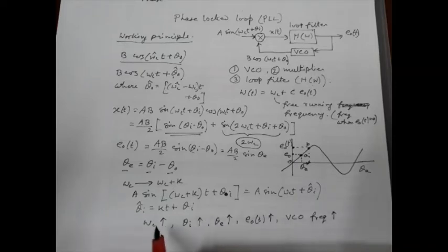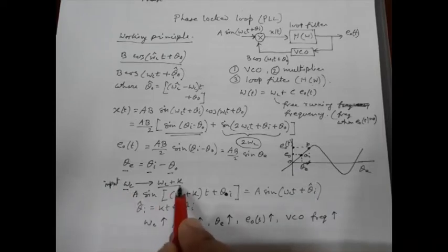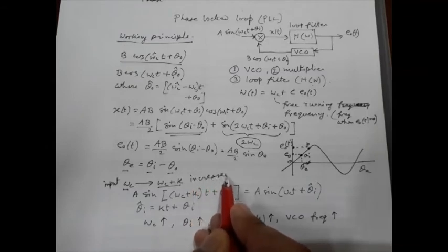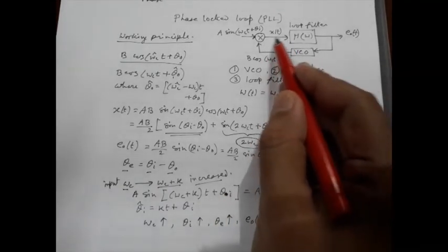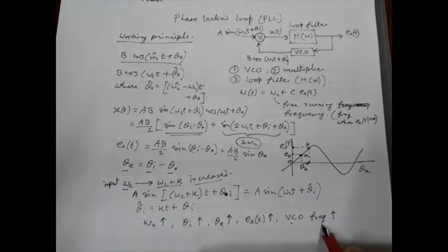That means originally we have assumed that the input frequency was increased, and now because of this feedback system we are seeing that the VCO frequency is also increased.